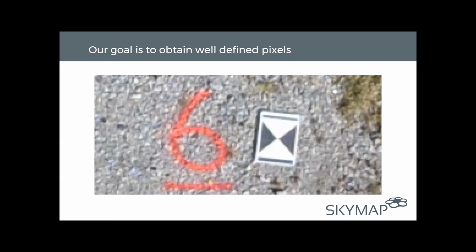Motion blur and overexposure are the biggest enemies of photogrammetry. Motion blur and/or out of focus photographs will cause noise as well as incorrect data. Overexposure or white pixels will cause incorrect data or sometimes even holes in the model. White pixels are dead pixels. You cannot do anything with a white pixel. You can't make it darker, and it obtains no information whatsoever. It is better to underexpose than to overexpose.